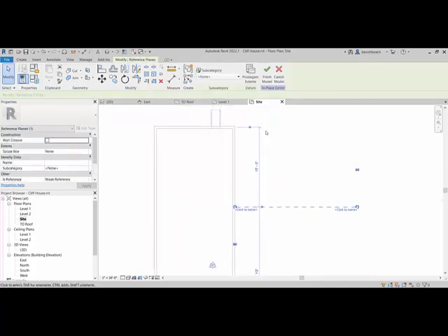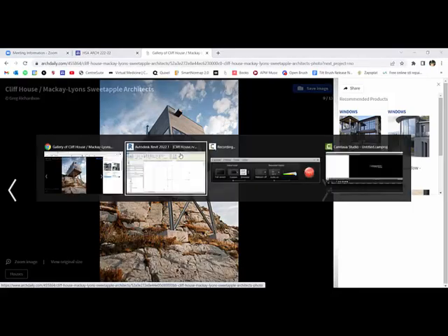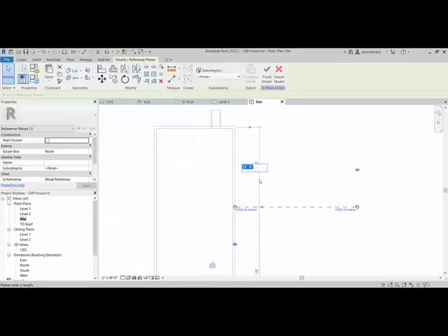And then we need to give a good sort of understanding of how far back that is from that edge. I'd say somewhere around 10 feet. You know, if I took 3 windows right here, it's somewhere right around that mark. So I'm going to set that reference plane 10 feet off the outside edge of the wall.